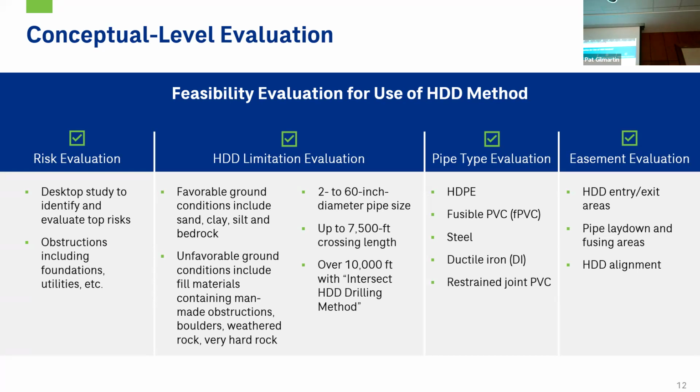Additionally, we'll want to look for obstructions such as foundations. If we do have our plan and profiles, we look to figure out if there are any utilities that we need to go under, or other critical underground items that we're aware of before the construction, though sometimes you're figuring these out after you've started your HDD.